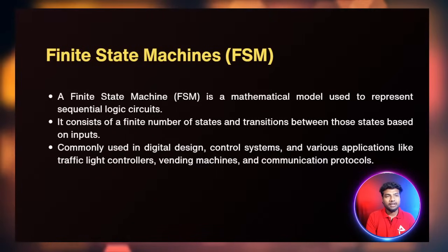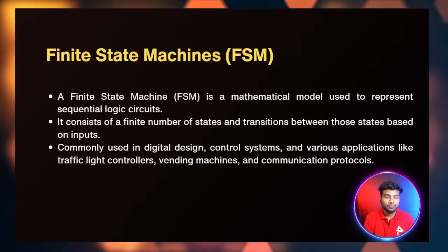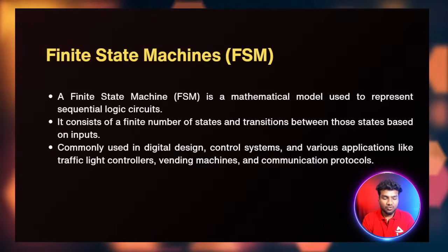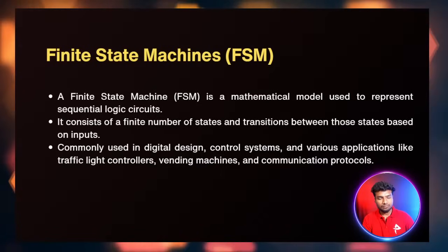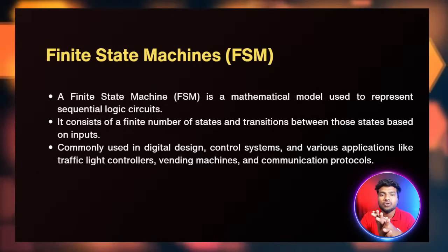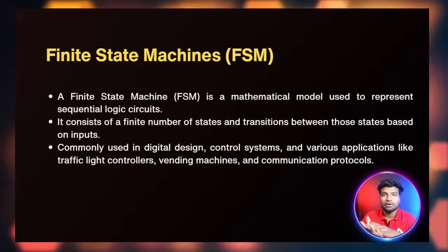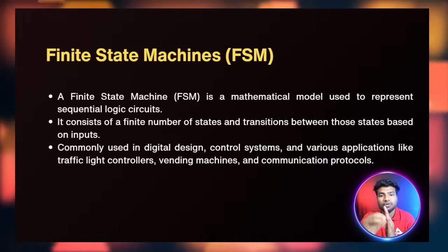FSM is a mathematical model used to represent a sequential logic circuit. It consists of a finite number of states and transitions between the states based on the inputs. It is commonly used in digital design. If you want to achieve one logic in sequential logic, you can divide it into several parts. Firstly you have to complete one state and then you can move to the next state.